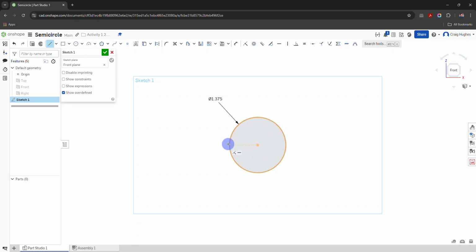If you notice, when I'm right at the center and I'm right on the edge of the circle like shown, I'm going to click and draw a line that goes all the way across, and you can see how it snaps into place. I'm going to go until I get all the way across. And notice how the line tool wants to keep following me around. So if I right click and select escape line, that'll stop that.